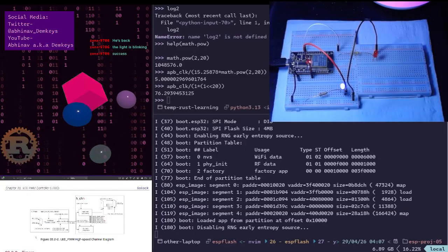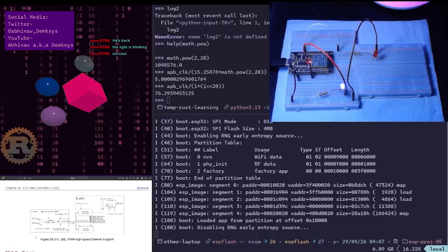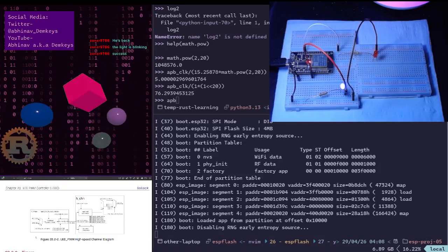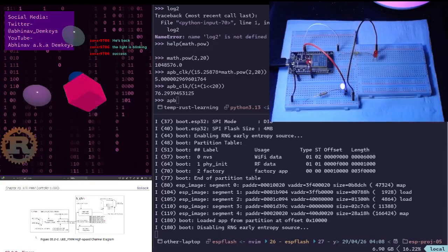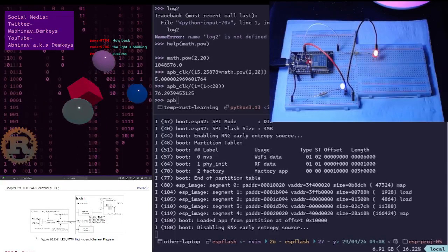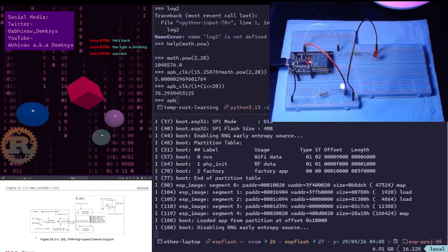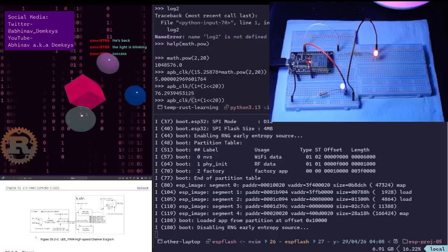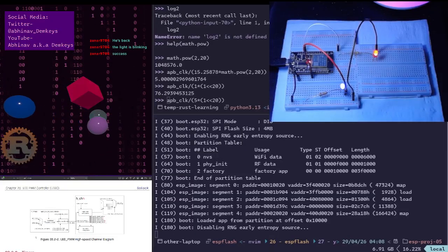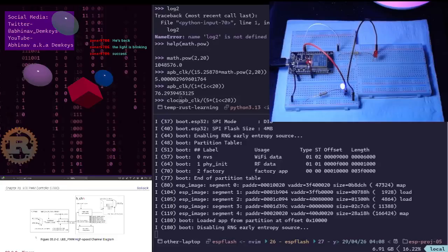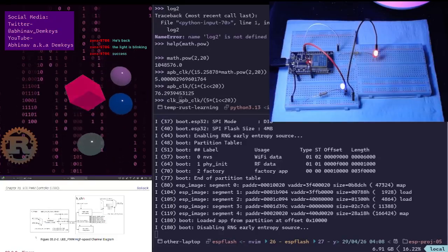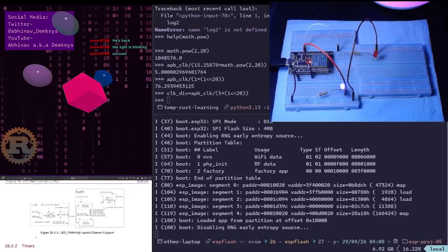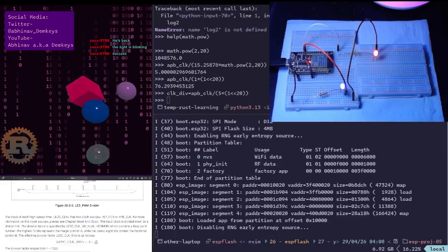80 million ticks. If we divide that into, so we have APB clock. What is our divider? Our divider is 15.2578 something. Wait, let me do this. Okay, so for 5 hertz, let's say CLK div equals this, and then we would just be dividing it by that amount, isn't it?